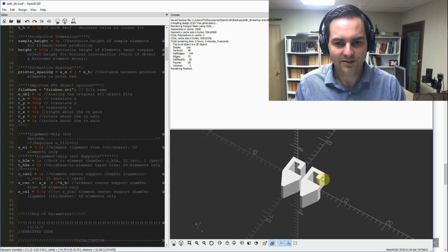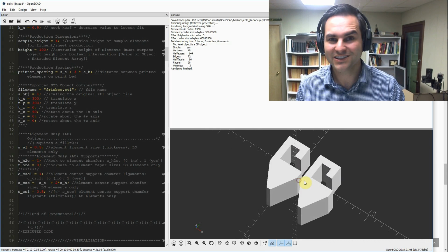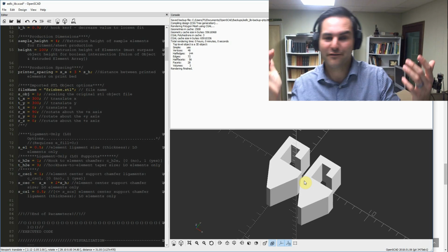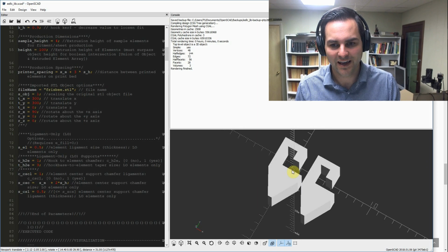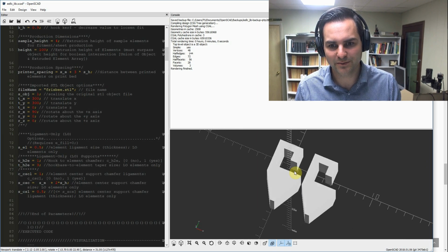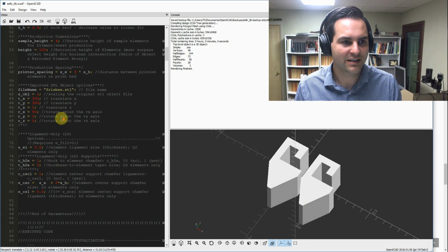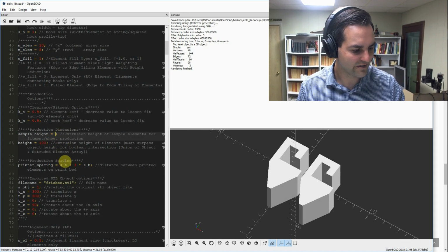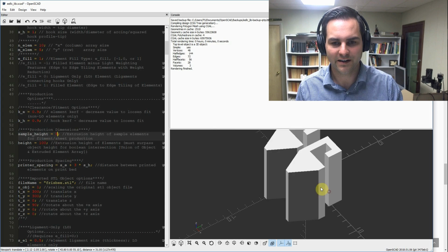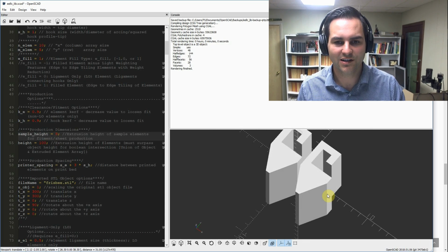I apologize. So now it has the two hooks side by side. You print those. That should take half a minute or something, depending on your hook size. If I was referring to millimeters, it looks like my hook diameter is less than a millimeter. So just do some real quick prints. And you can adjust the sample height here in your parameters. If you don't believe that they'd fit well over a long distance, then make the sample height taller.